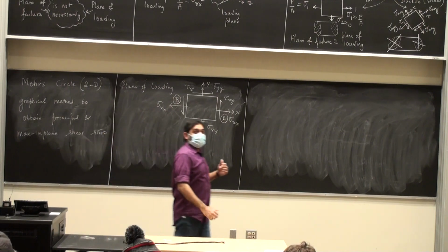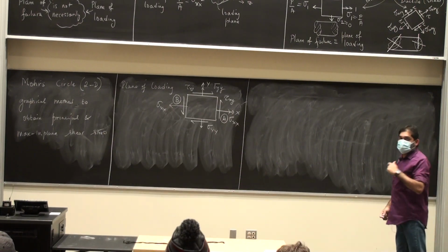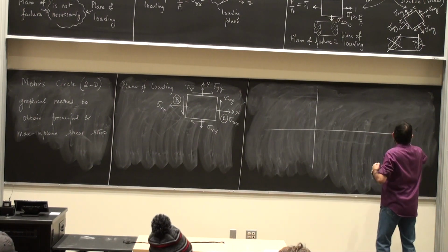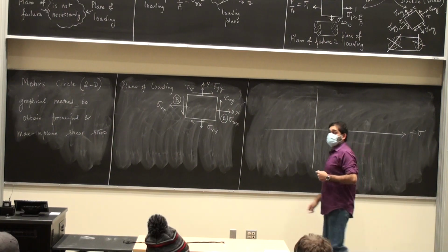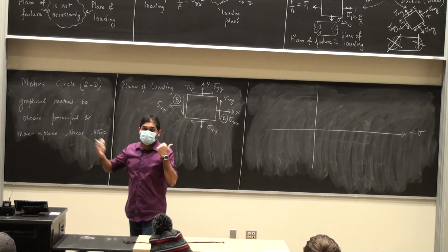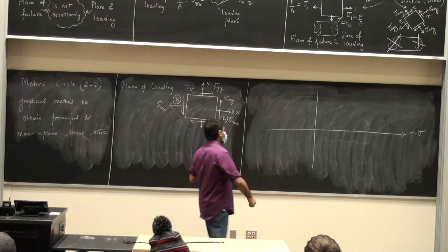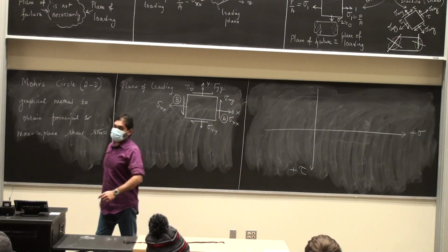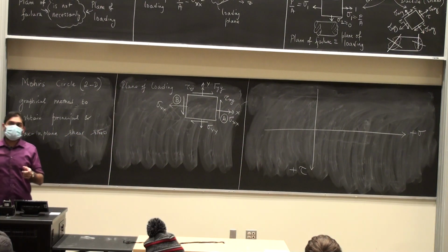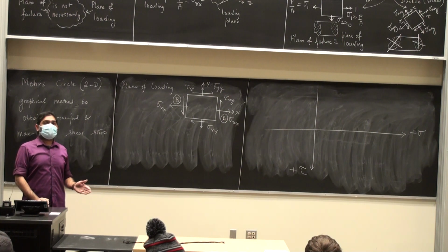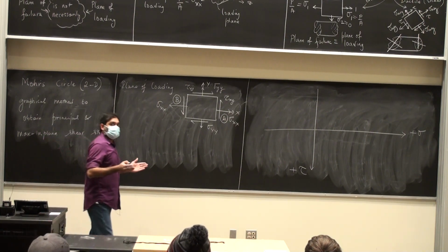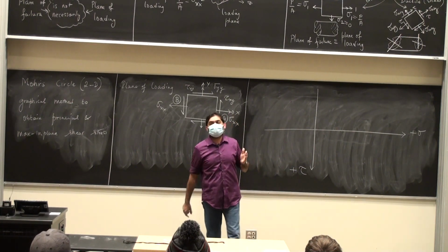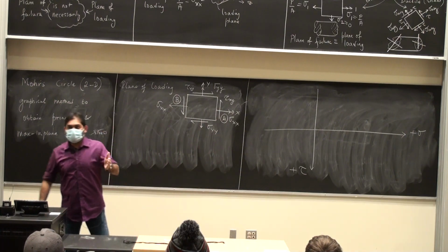Then you set up an x and a y axis. Be careful, this is how Mohr defines it, so if you have questions you can ask him. Positive sigma on the positive horizontal side, right side, and then positive shear stress, look at this, on the negative y axis. By definition of how Otto Mohr came up with this technique. And why did he do this? Because only if you do this will the answers that you get from this technique gel with the theory. Otherwise it will be wrong.